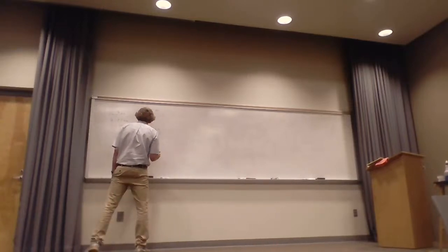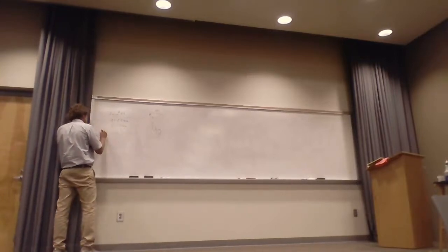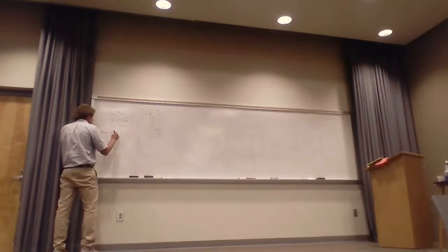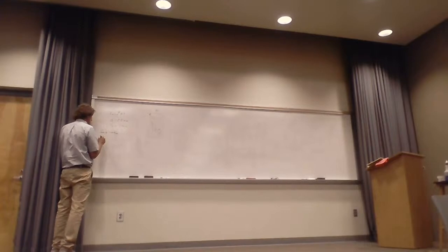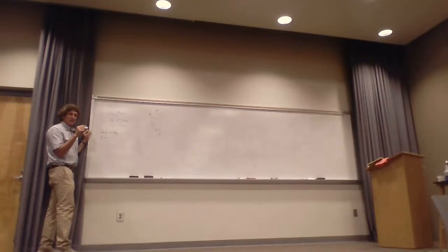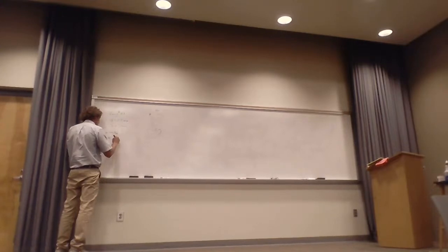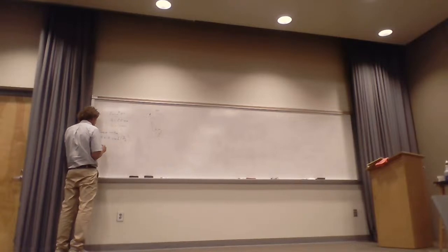Now, when you're doing this, you have to get the skin depths. Let's talk about the one for gold. Gold, the symbol is AU. And for gold, the conductivity, can you tell me what that is? I don't remember it off the top of my head. 4.1 times 10 to the 7. And the units are Siemens per meter, 1 over ohm meters. That's for gold.